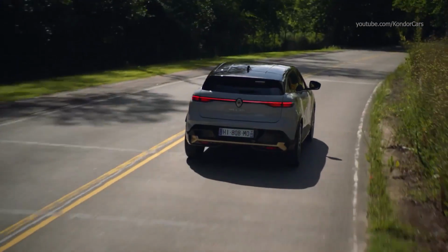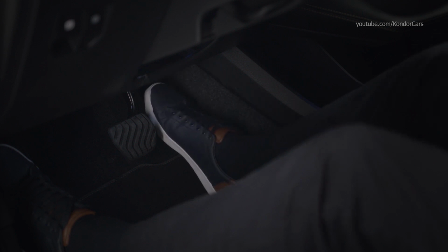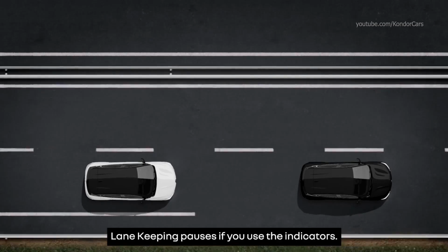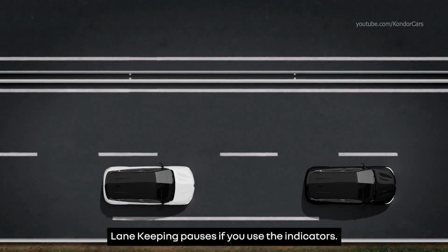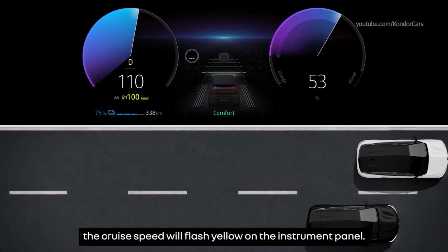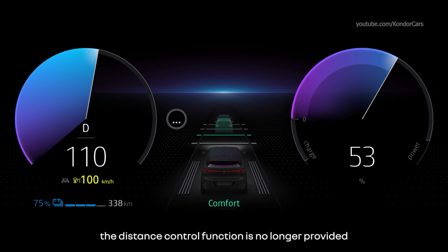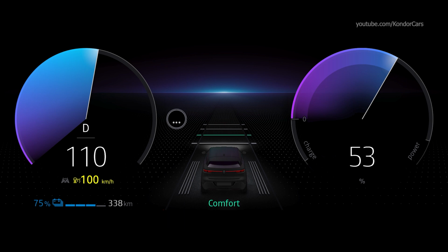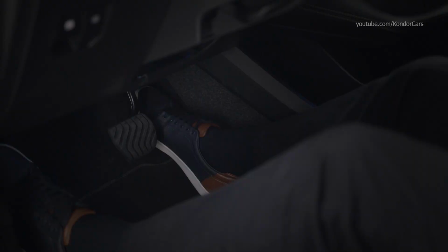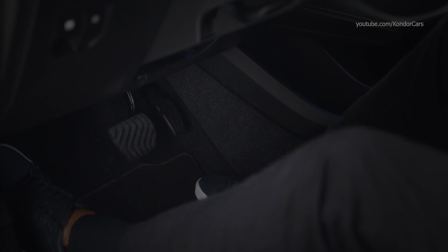Also, you can exceed the cruise speed and overtake at any time just by pressing the accelerator pedal. Lane keeping pauses if you use the indicators. While you're overtaking, the cruise speed will flash yellow on the instrument panel. If the distance from the vehicle in front is less than you have selected, the distance control function is no longer provided and the programmed following distance bar flashes on the instrument panel. When you've finished overtaking, gently release the accelerator pedal to restart Active Driver Assist.